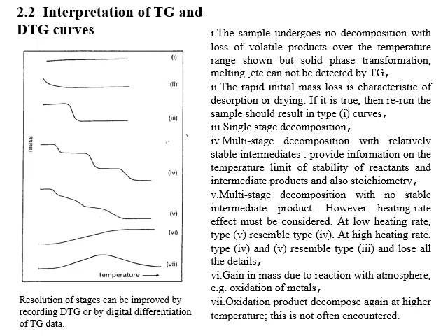And as the bullet point indicates, if this is true, then rerunning the sample immediately after, before moisture reabsorbs to the sample, should result in a flat line. And you almost always see this in the beginning of TGA curves if you haven't actually dried the sample prior to doing it.